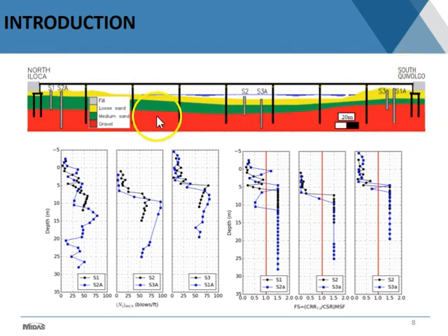Now, if you take a look at the simplified soil profiles found at the site, of course you have the fills that are the abutments, but in terms of natural soils, you have an upper loose sand, marked with yellow here. Underneath that layer, you have a medium sand, and then you have a gravel deposit that is rather dense.